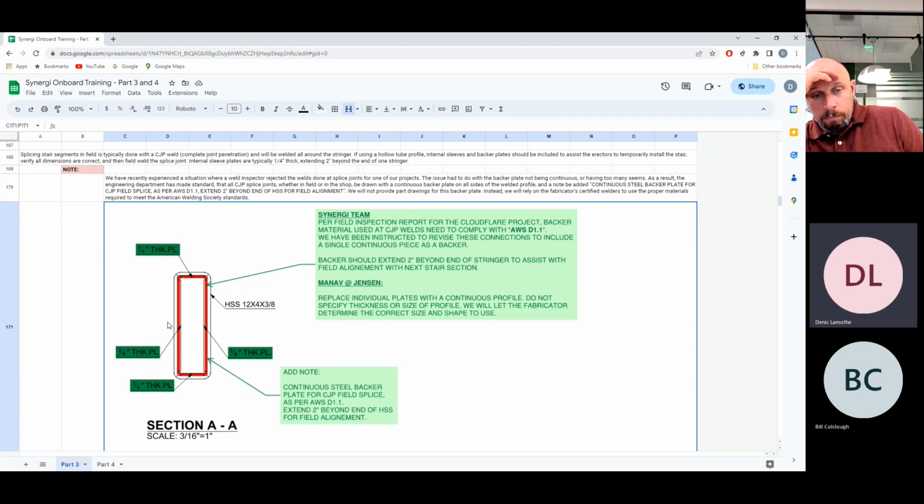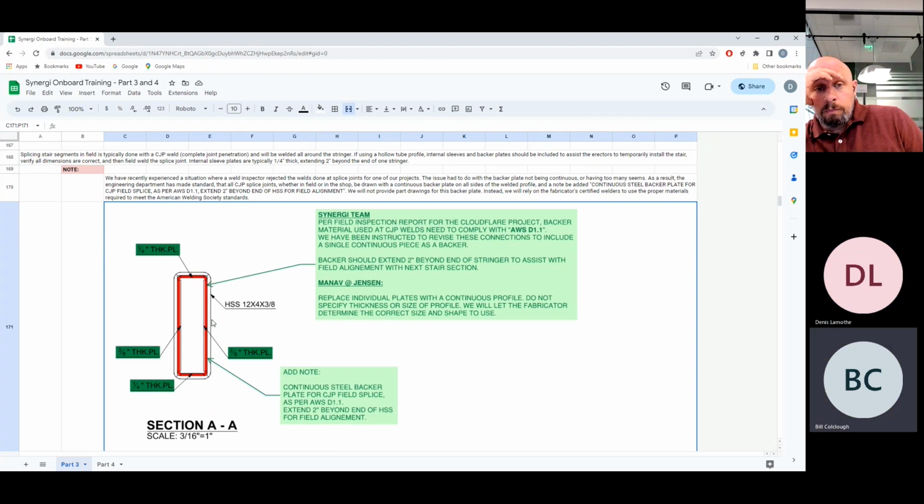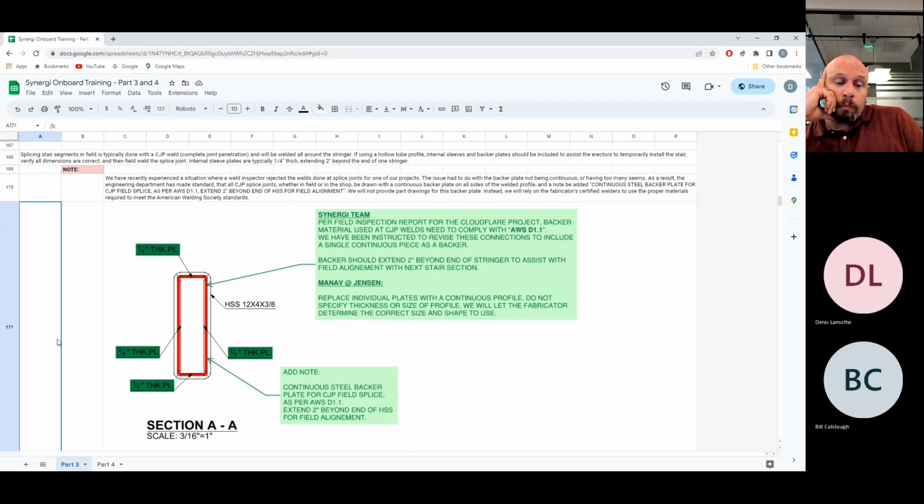So the weld preparation, the beveled edges, and the notes not to add a finish, whether it's paint or primer, at about 2 inches away from the edge of the profile that will receive the weld. Yeah, and that's both profiles. So when they're mated together, right at the joints, it's 2 inches on the one side and 2 inches on the other side. All right.